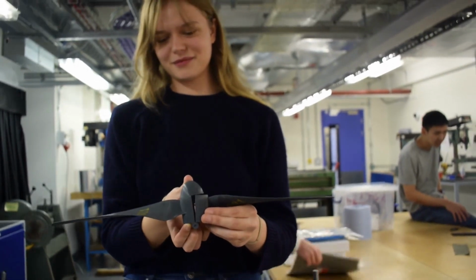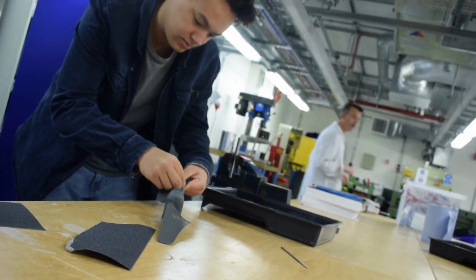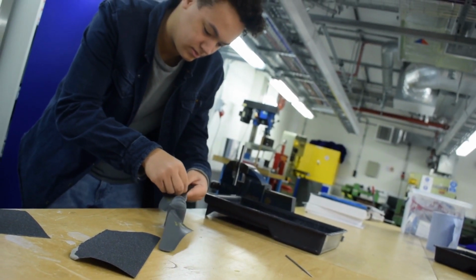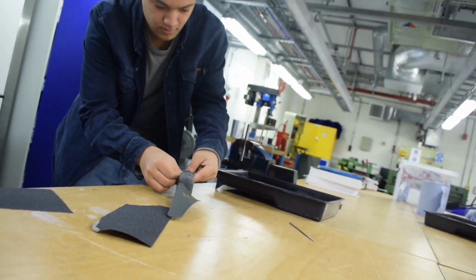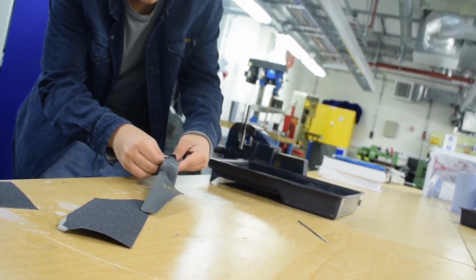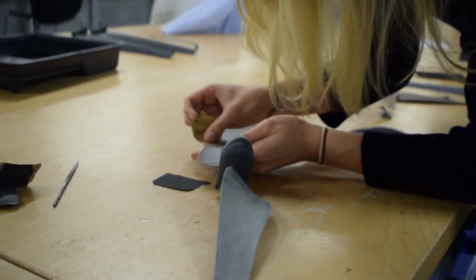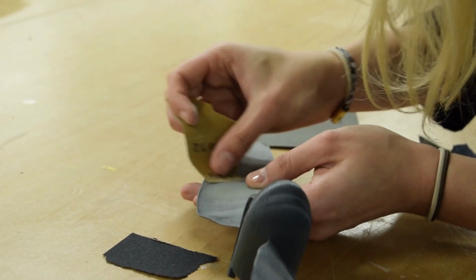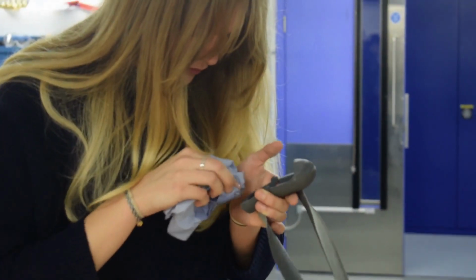The 3D print was largely successful. The hinge printed really well, allowing the two halves of the nose cone to slot together. To reduce friction drag over the blades, the surface was sanded to remove printing artifacts and to ensure it was as smooth and slippery as possible. This was achieved by starting at a very coarse sandpaper to remove large printing defects, and then increasing the fineness of the sandpaper until the whole blade surface was smooth to the touch. The rail on the trailing edge was also sanded off, making sure the trailing edge did not become sharp so that the flow would leave smoothly.